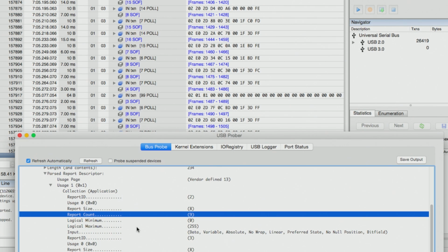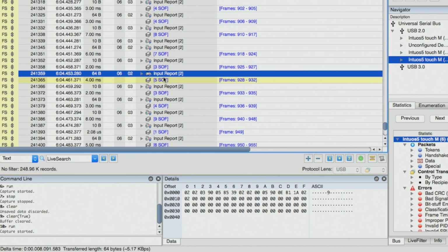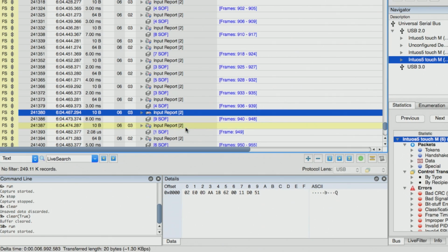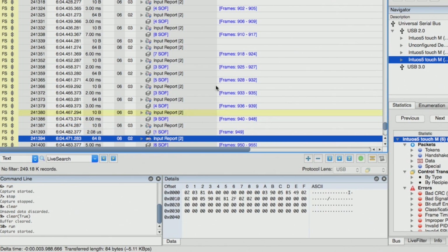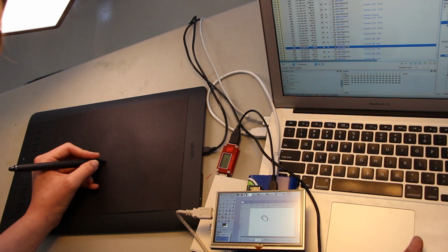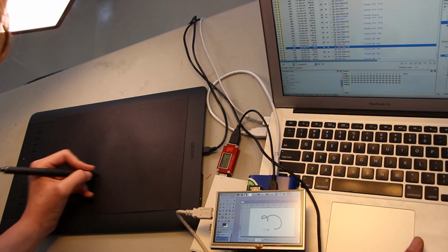But the descriptor here doesn't say anything about what those 9 bytes are. So unfortunately, this is also something you see pretty often with HID. HID here is just being used as a wrapper for a completely opaque vendor-specific protocol. So although we can reasonably guess what these bytes might be for by doing some experiments, the descriptors don't actually explain them to us like in a standard device.